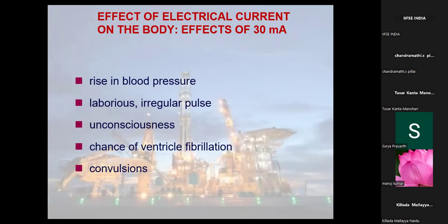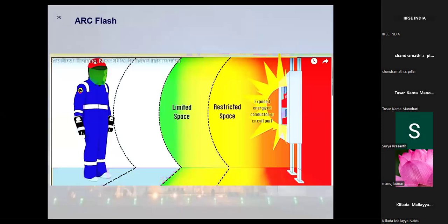Then coming to production industry where fine dust can cause static electricity discharge, such zones we mark as 20, 21 and 22. Zone 20 is dangerous. Zone 21 is less, 50-50. Zone 22 is 25-75, 25% dangerous and 75% safe. Similarly, for arc flash, you have different types of zones.